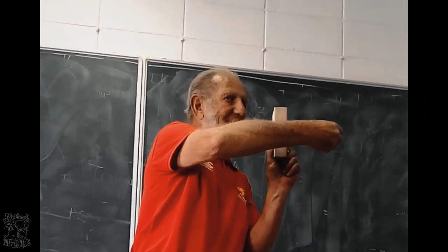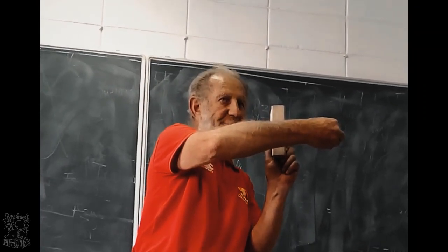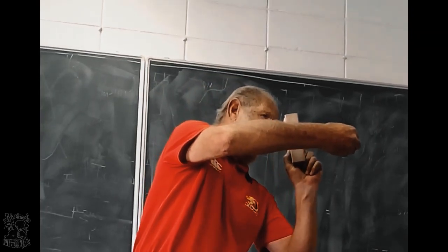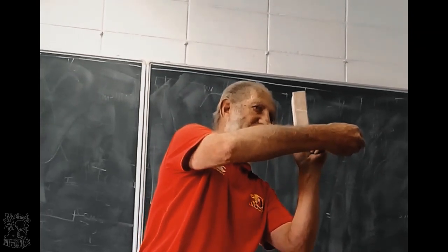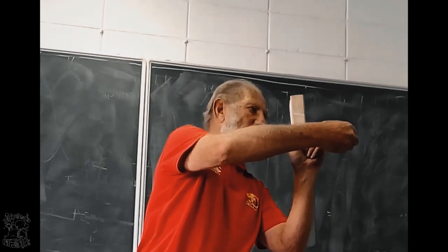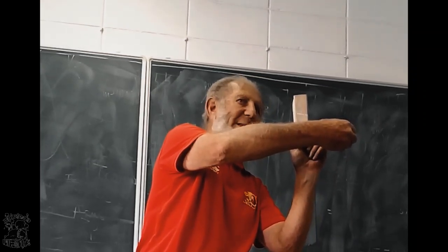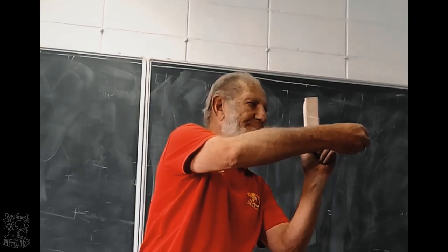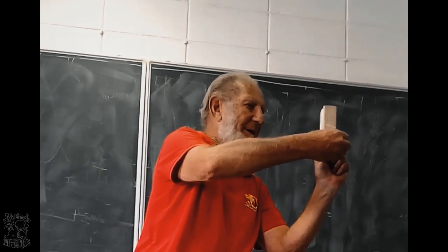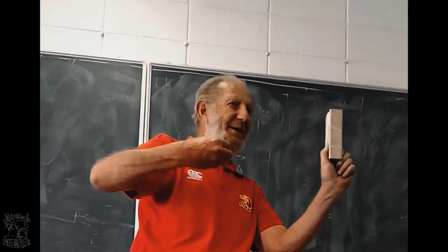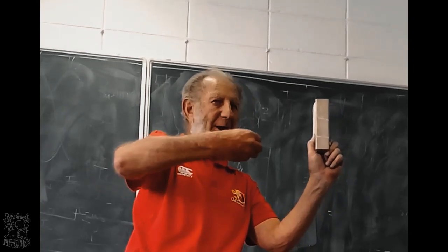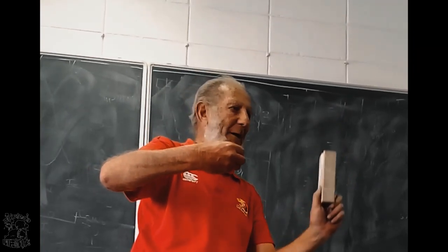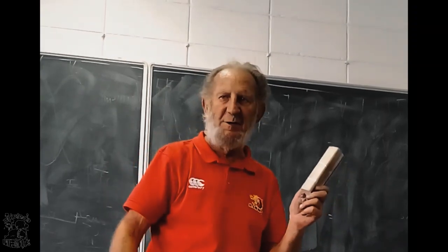Then, when it comes out this side, it's going to touch a switch, which will put power on this cylinder. This cylinder is going to move up. When it comes on the top, it touches a switch, which loses power on this cylinder. It comes back. It cuts another groove. And then, when it's back, this one loses power, it comes back, I can take the job out.